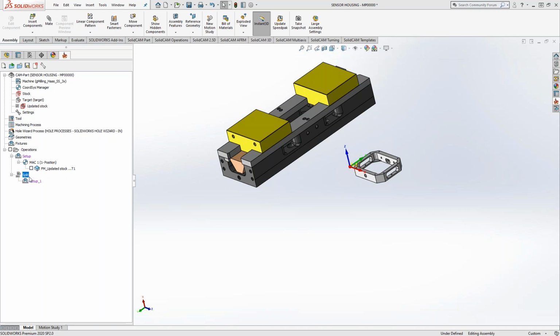So the other way to do this is saving that STL we talked about yesterday. You'd have to save the STL and load it in another CAM part file to get that same functionality, that same associativity. But if you do all your setups in the same CAM part file, then you don't have to do that. That STL is already being saved for you in the background. The only time you have to do the STL option is when you're changing the post.